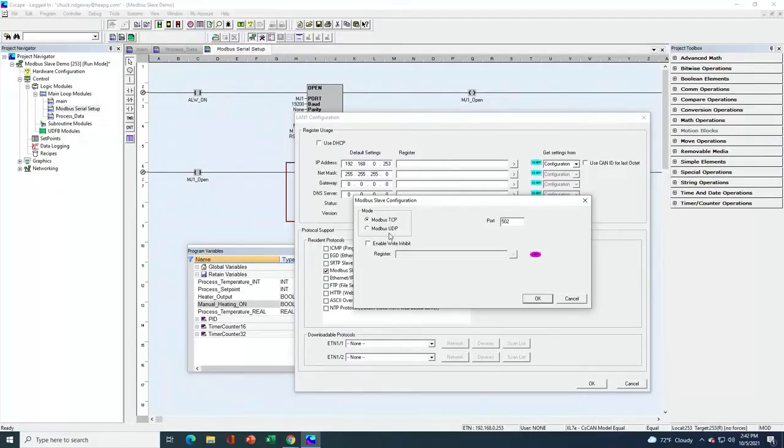But if my message fails, I know it, and I can then just retry again or not retry if that's what I want to do. So with Modbus UDP, you have more control over how much data actually goes out over the wire because there's no retry mechanism built into Modbus UDP. So we've got some customers that prefer to use that, especially with cellular modems or satellite modems.